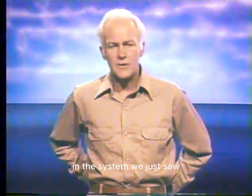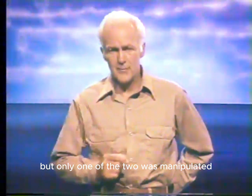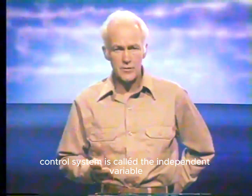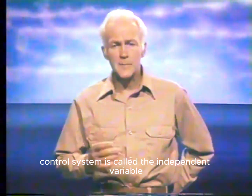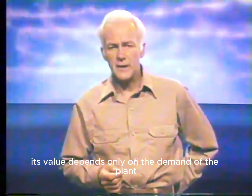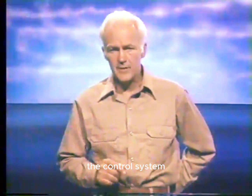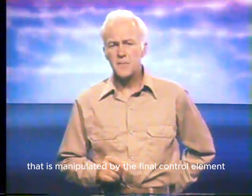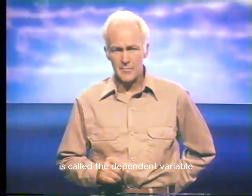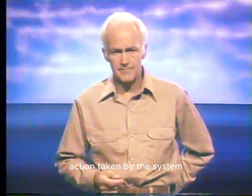In the system we just saw, two variables were monitored, but only one of the two was manipulated. The variable that's not manipulated in a ratio control system is called the independent variable. Its value depends only on the demand of the plant and is independent of any action taken by the control system. The variable that is manipulated by the final control element is called the dependent variable because its value depends on the control action taken by the system.